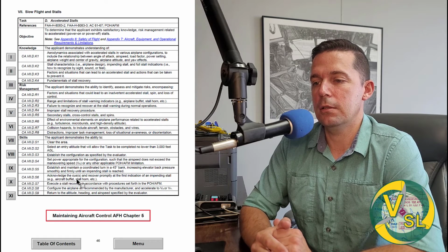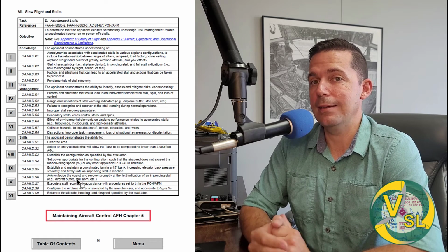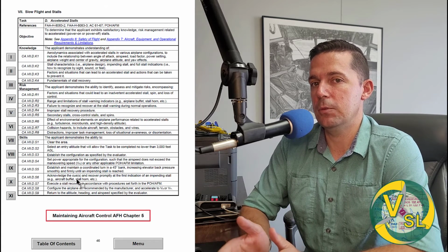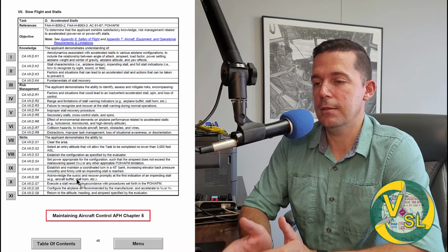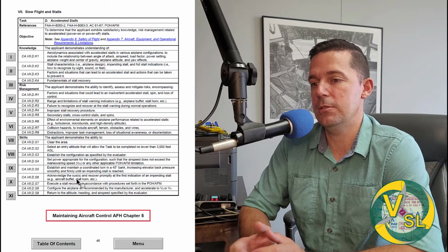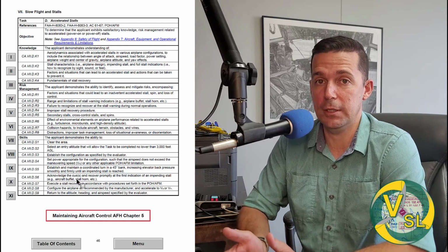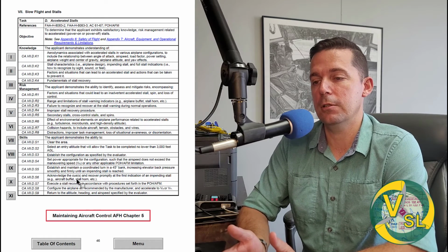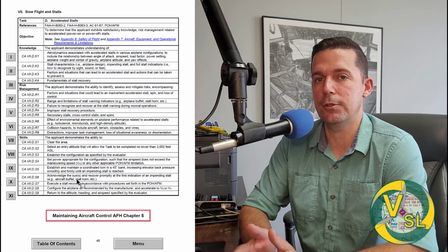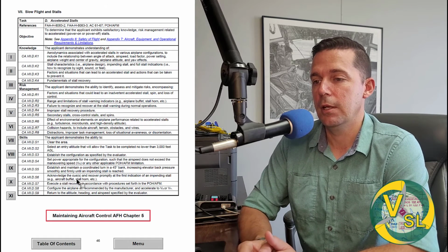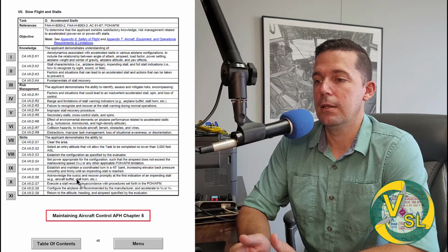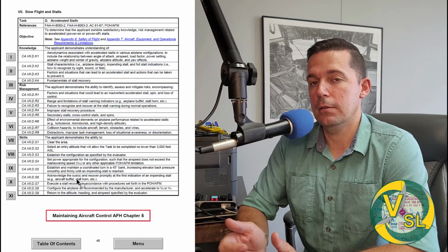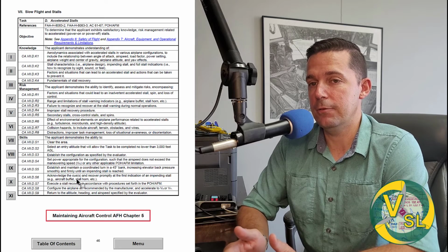So this is something that I teach all my private pilot and commercial pilot students, that correlation between load factor, or G's, and our stall speed. We're just demonstrating that the plane can stall at any airspeed here. That's really what we're doing. You've heard that before from your instructor, I'm sure, that an airplane stalls at a critical angle of attack, not an airspeed. So in an accelerated stall, we can increase our stalling speed by increasing load factor.